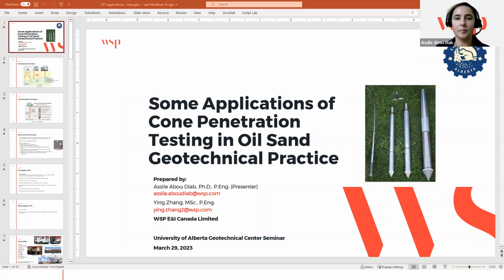For those zones that were identified as potentially liquefiable, we run some more geotechnical analysis, and based on that, we decide if we need remedial measures, and it is really case by case. So we may do some more compaction of the cells, or in some other cases, if there is room to add a buttress, we would buttress. So it's really case by case. And as you mentioned, maybe soil improvement techniques may also work.